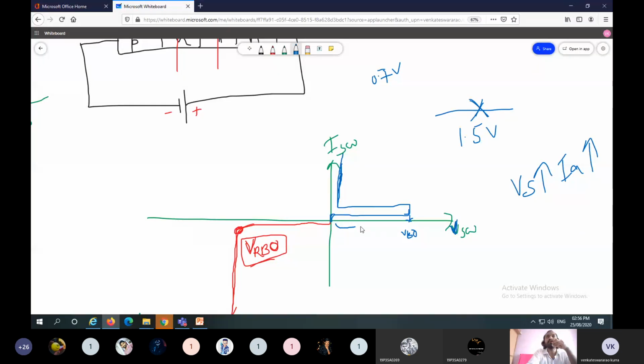If the supply voltage goes beyond the breakover voltage, it starts conduction and the voltage across the switch falls to some 1.5 volts. With increasing supply voltage, the current flowing through the device, which is nothing but the anode current, increases. These are the three states of